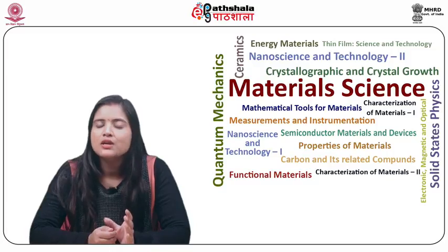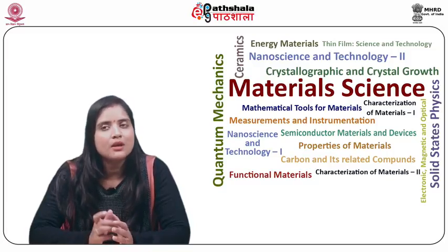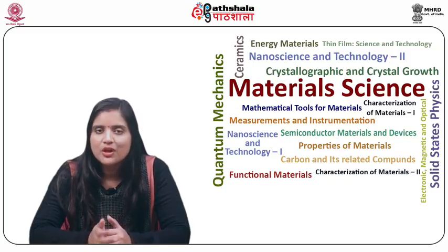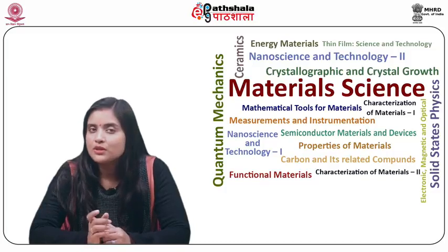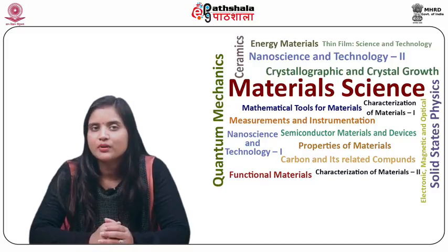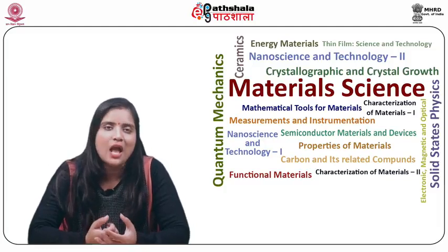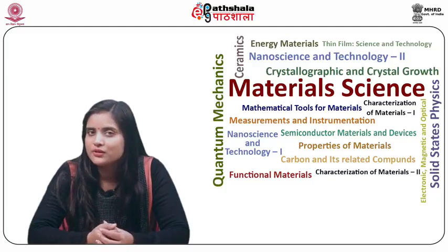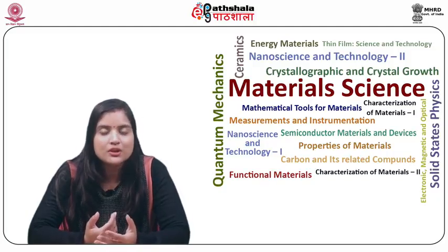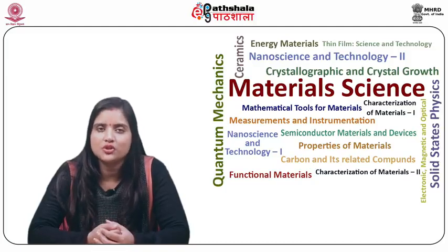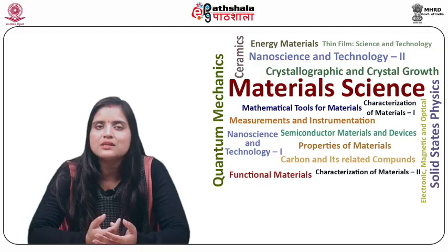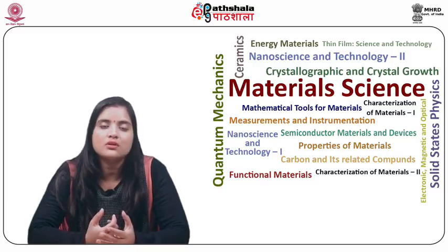It is well recognized that the majority of inorganic materials become soluble in water at high temperatures and high pressures. The hydrothermal method is based on the premise wherein the materials are dissolved in water under high temperature and pressure conditions. These dissolved substances are then crystallized to obtain the desired end products. As indicated in the name, water performs a crucial role in the precursor material transformation process at elevated temperatures. According to the phase diagram of water, merely the branch between gaseous and liquid state warrants further consideration.